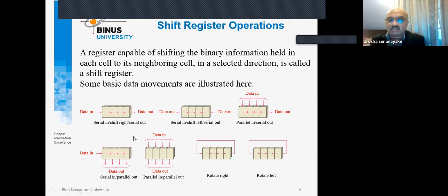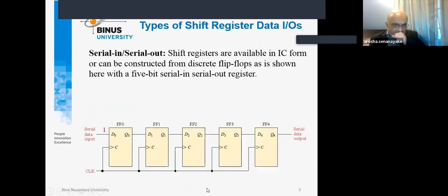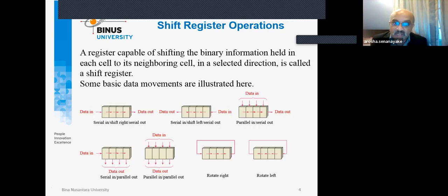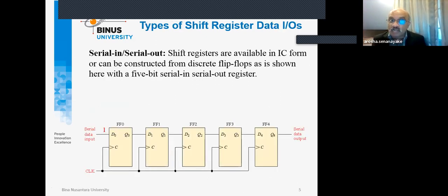So utilized some time really for ALU operations as well. Okay. So then serial in, serial out registers, as I explained to you a short while ago: each box in this slide implies a D-type flip-flop. Why? Because a D-type flip-flop can store only one bit